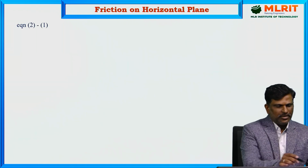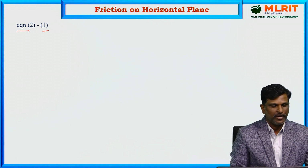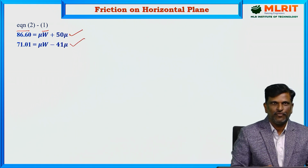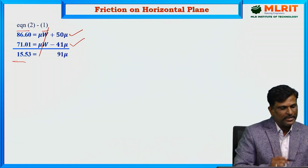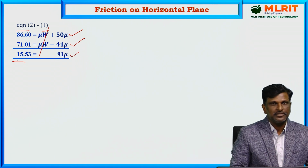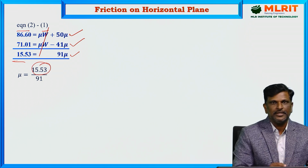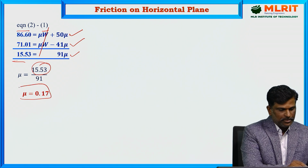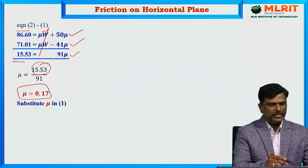Now subtract equation number 1 from equation number 2. Doing the subtraction, we get 15.59 is equal to 91 mu. From this we can calculate the mu value. Mu is equal to 15.59 divided by 91. The value of mu, the coefficient of friction, is 0.17.